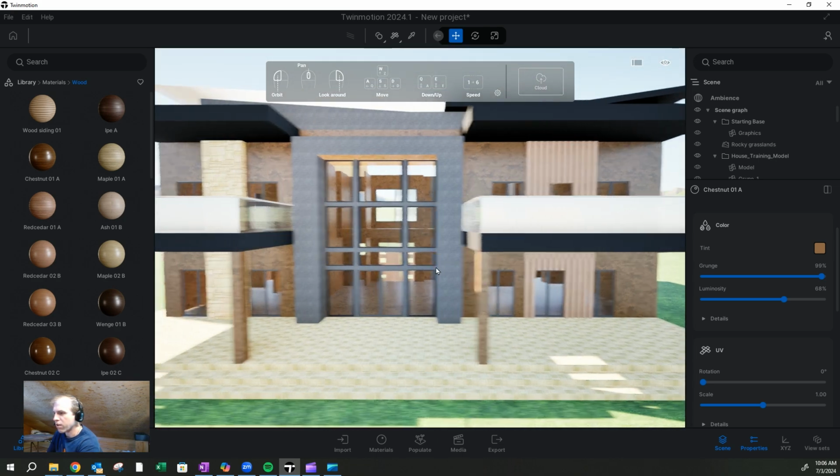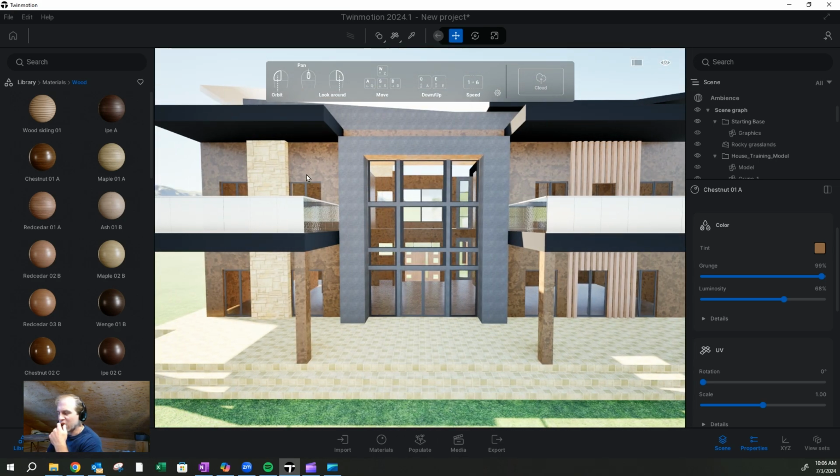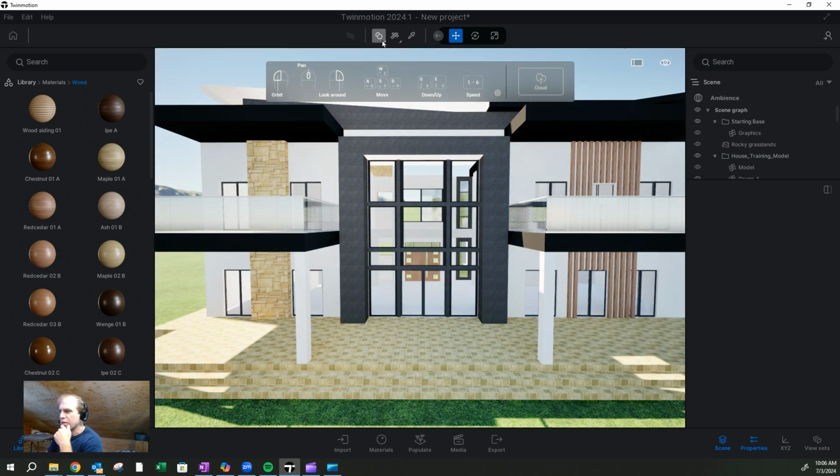And it looks like in the model that I imported, the material for these exterior walls was the same, so it changed everything. Some ways we can counteract that is if we come up here to this material and you replace by material or apply to that specific object.